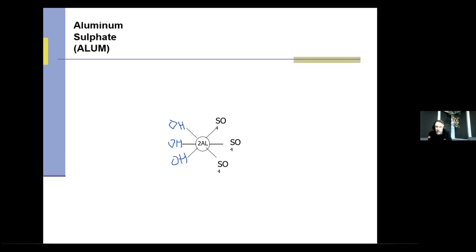Of course, the product is probably more expensive, but I don't have to adjust any chemistry. It's going to work in my favor. And that is called polyaluminum chloride, or PAC as it's called. And it's built-in alkalinity, which is great.